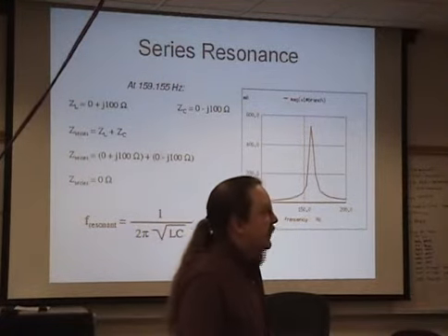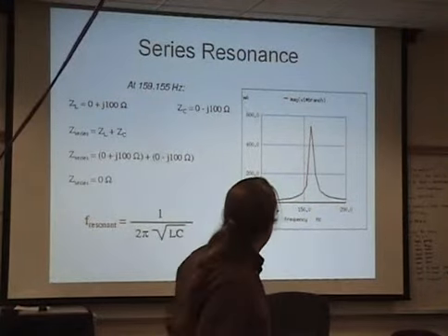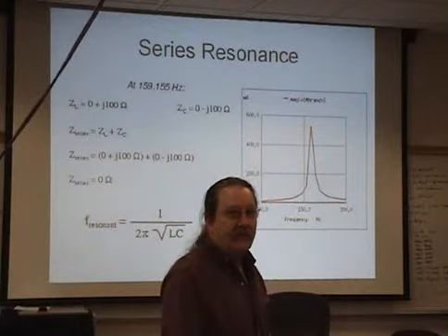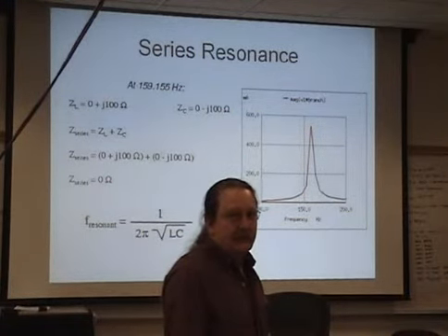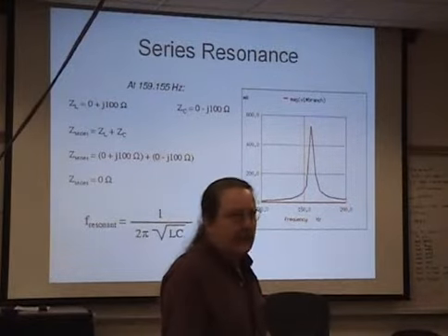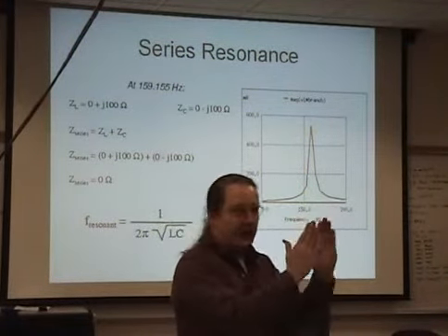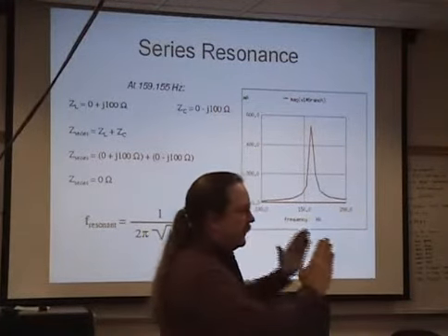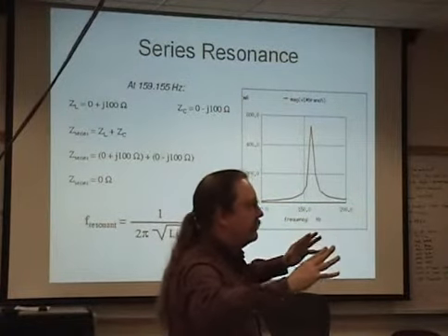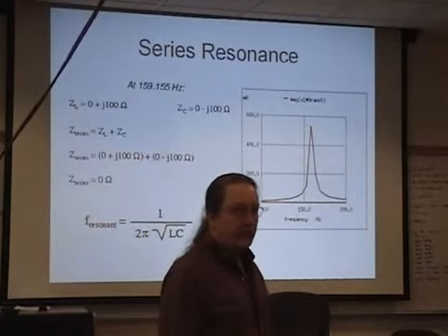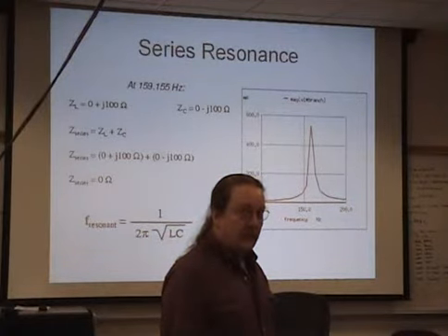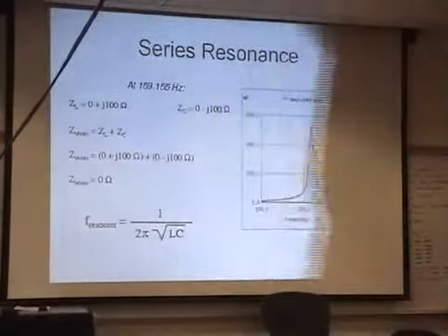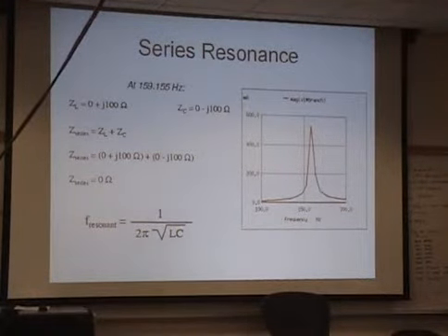Radiation patterns illustrate the way antennas radiate in the horizontal and vertical dimensions. Patterns can be analyzed through antenna modeling software. I'm going to have a few examples of that later if you want to get really bold and model your whole antenna farm to find out how all your antennas interact, or for you, how your dipole interacts with the roof of your building. And for me, I have hemlock trees, and when the hemlock trees are wet, 440 goes away. I can't get out unless I really boost the power. Hemlock trees are dry, not a problem. Interaction between various antennas, and well, I just said that. Okay.